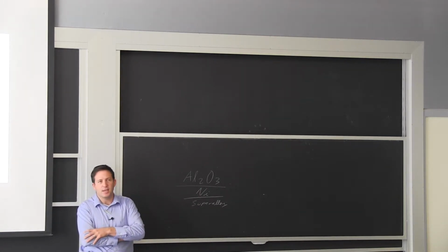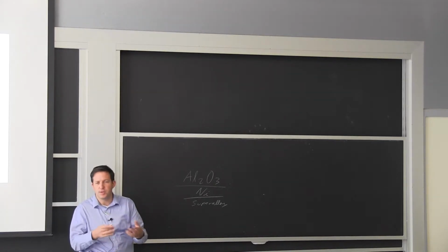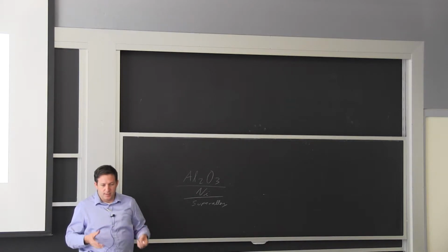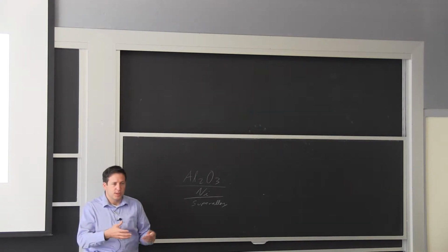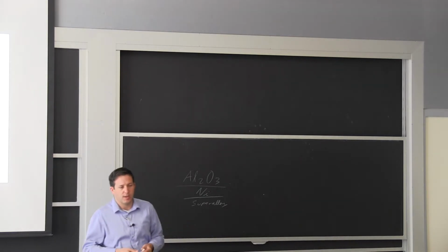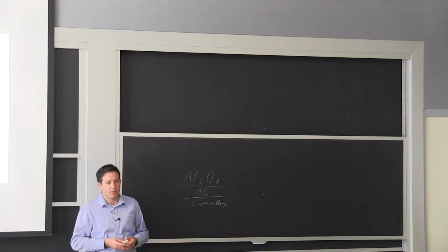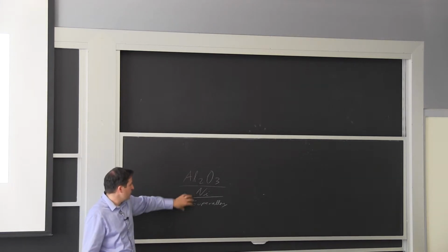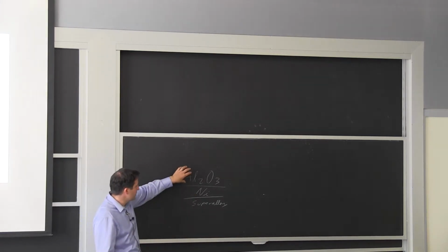So you can get as much as 50% volume dispersion into a superalloy. So it's kind of a two-phase structure, and the dislocation can go through from one to the other because of that coherence. The very same way you strengthen aluminum alloy is how you make a good superalloy, essentially. So from here to here, your temperature keeps going up. This is wanting to expand less.